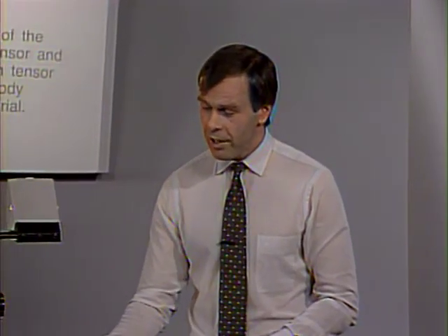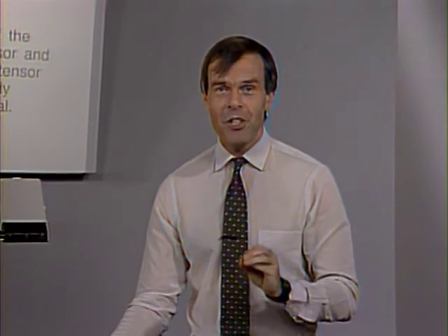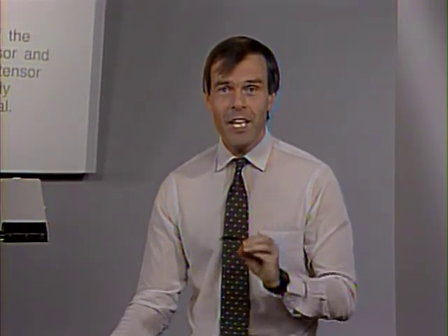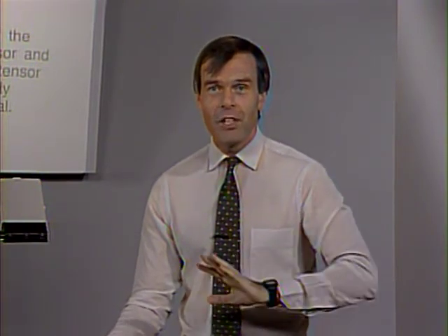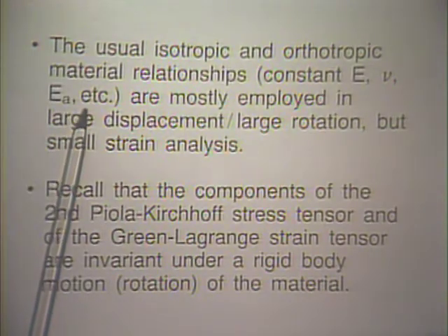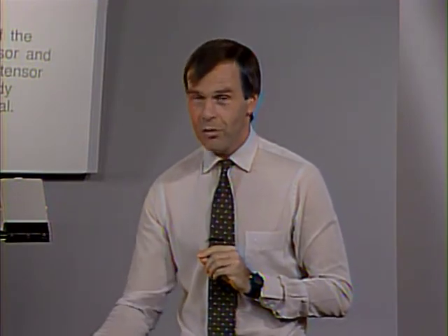And this is most important because we use this fact to apply material descriptions that are applicable to small strain analysis directly also to large displacement, large rotation analysis. E, nu, Ea are material constants applicable to small strain analysis, and we can directly use them also in large displacement, large rotation, but small strain analysis using this fact.